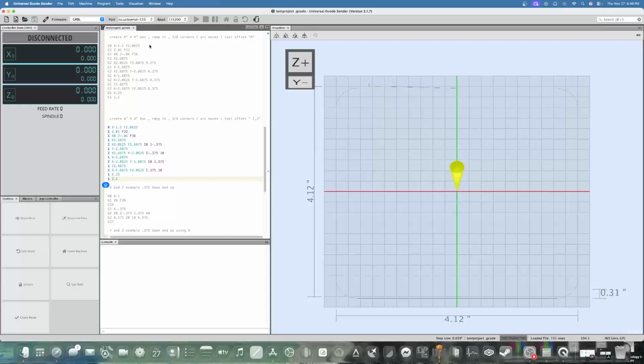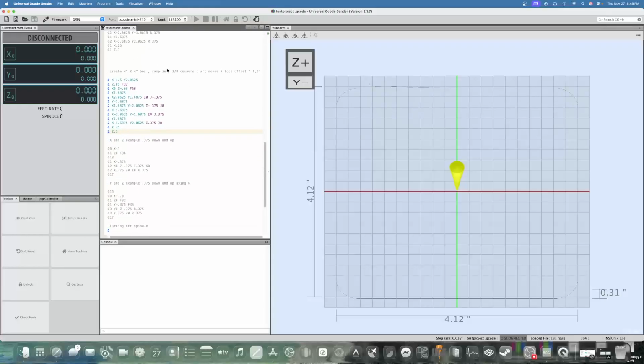Okay, this is basically the exact same G-code that's up here, with the exception that we're replacing R with I and J. And again, I is X, J is Y. We follow along this. We get down here to the stop point. We're fixing to do that first radius.